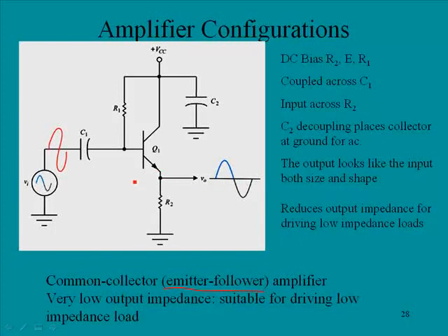Okay. This particular circuit, we calculate the gain to be 1. So you say, well, what in the world are we doing with this? There's no gain. I don't see any amplification here. Well, what we have here is a circuit that is suitable for driving low impedance loads. Remember we said that with a signal source or an amplifier, we want to have low output impedance. Well, when we take a signal off of the emitter, it steps the impedance down significantly.